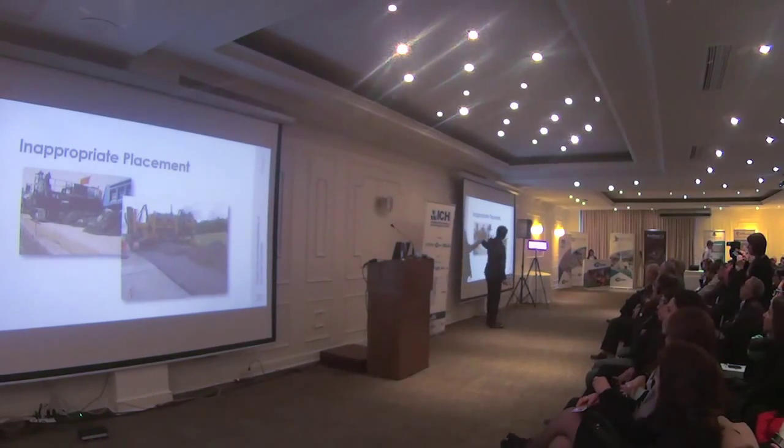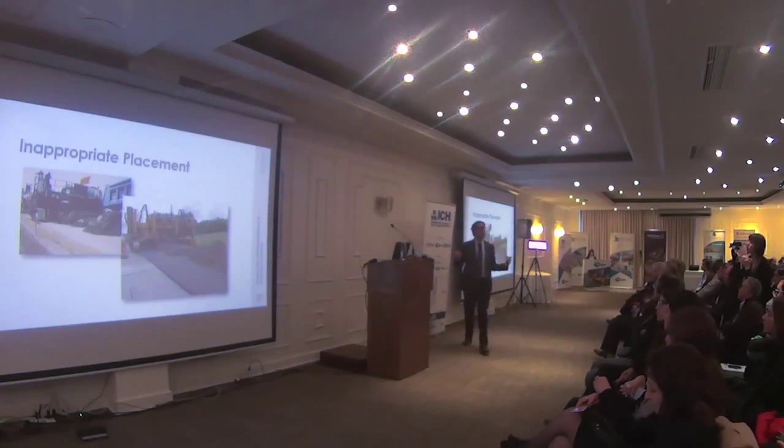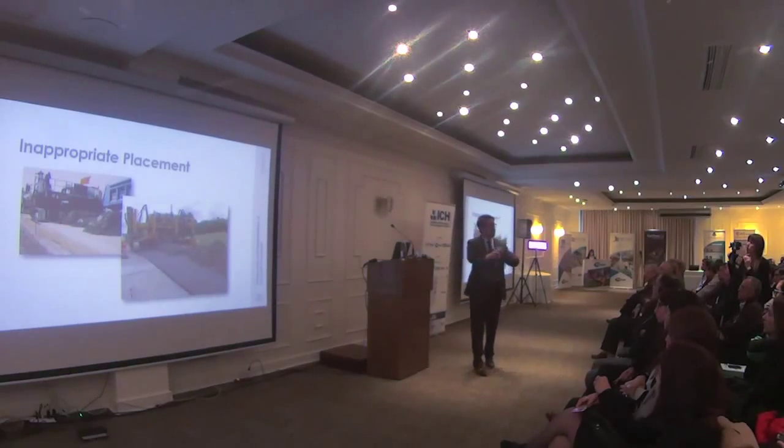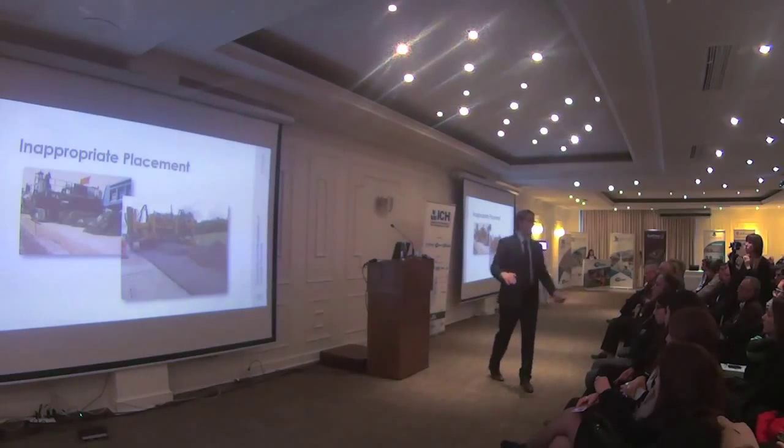This, right here, is one of the biggest contributors to roughness in concrete pavement construction with slip-form equipment. Because the slip-form paver is running on Caterpillar tracks, moving forward. If it hits a big wall of concrete, it has to spread that. It pushes back against it, and it almost lifts the paver up just a little bit as it tries to fight over the top of that mound.